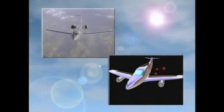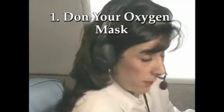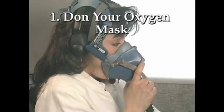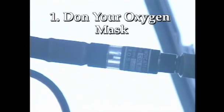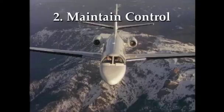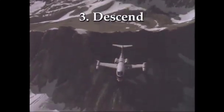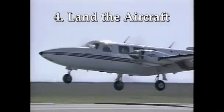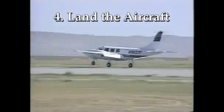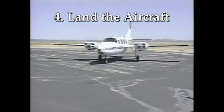If you experience a decompression, you should use the following procedures. 1. Don your oxygen mask. You should be able to do this in 5 seconds or less. Check to make sure the air is flowing 100% in your mask. 2. Maintain aircraft control. 3. Descend to a lower altitude, preferably 10,000 feet or below. 4. Land the aircraft as soon as possible, and if needed, obtain appropriate medical help from someone who is familiar with aviation physiology.